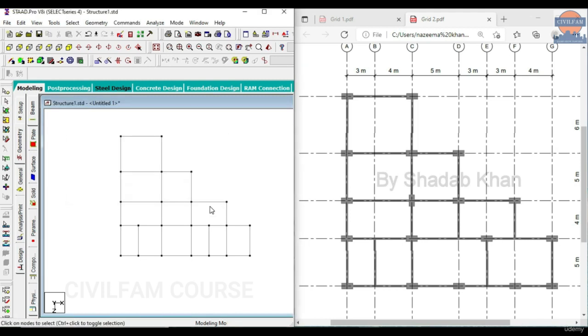All right, so again we come over here. We see this, and then I have to select this beam and delete it off because it's not existing anywhere. Then I have to repeat the same thing for this one as well. Editing here will take some more time. That's why I prefer going by translation repeat because I have more control over there. As I'm drawing it, I can do it. So you do this much and you'll end up with something that looks like the plan.